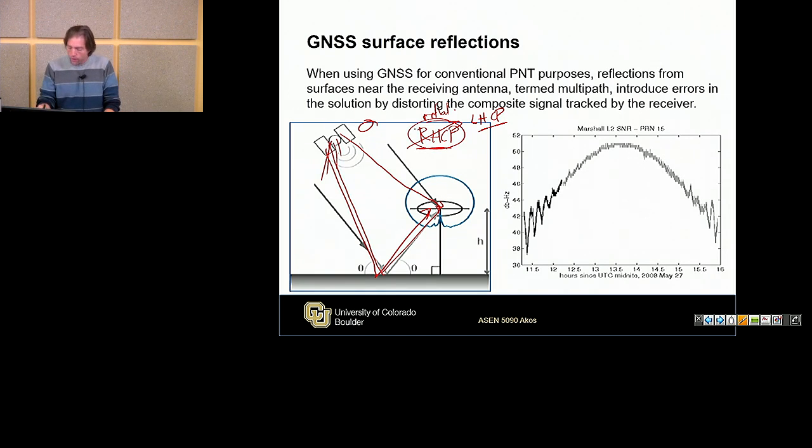So okay, we'll use these RHCP antennas. So when we have an LHCP signal, let's get rid of that. Let's see really what happens. If you look at it, the RHCP works pretty well for signals which are where you're looking for, up above 20, 30 degrees. But when you're trying to build an antenna, just because of the physics of trying to put that together as I understand it, it's harder to get that strong RHCP signal on these lower elevation angles.